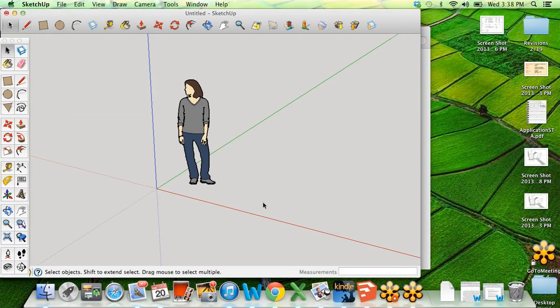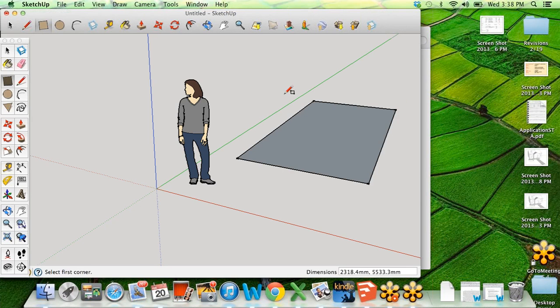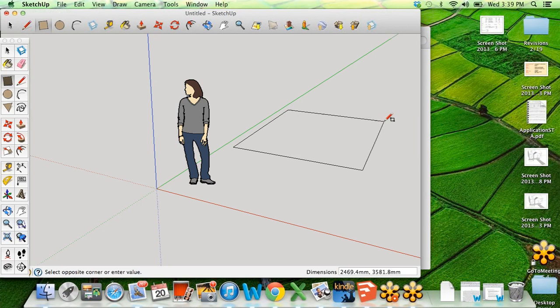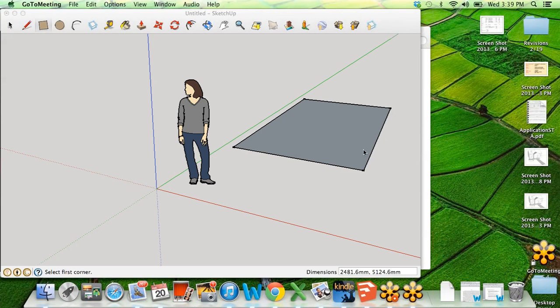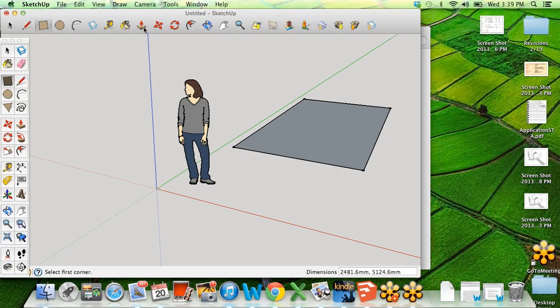Okay. So let's talk a little bit about rotating. I'm going to build a box by first building a rectangle, and I'm going to edit undo so that I can go over that again. When you're building a rectangle, make sure you get in the habit of clicking to start it, and then again clicking to finish it, as opposed to dragging that shape. It'll let you be more accurate. Okay? And to make it 3D, we use the push-pull button.